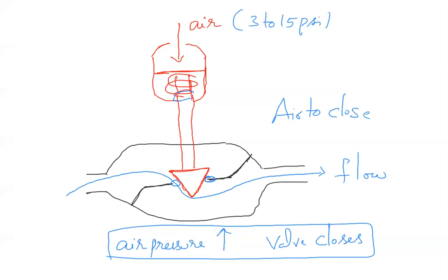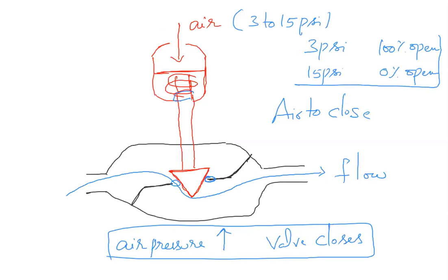That means for 3 psi, the lowest pressure, what is the position? The valve will be 100% open. For 15 psi, the maximum pressure, the valve will be 0% open. So with the air pressure, the valve closes.